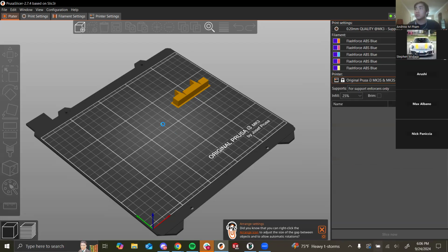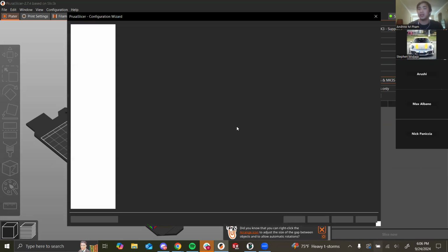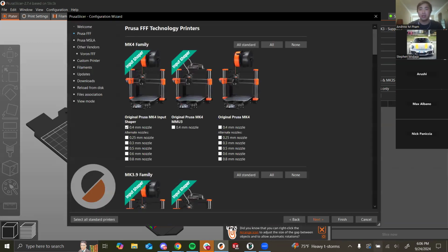Hi, Andrew. Say for example, you're trying to do some FEA on a thing you're trying to 3D print. What would you set the material to? I mean, you would just set it to the material that you're using. Generally, a common plastic would be a PLA or a PETG. I actually primarily print in something called ABS.